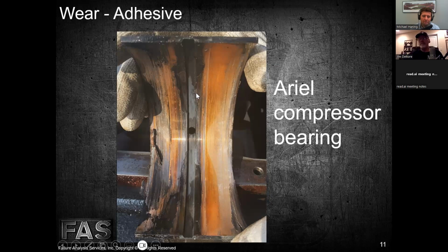We see all sorts of different issues related to crankshaft surface finish, clearance issues, alignment issues, soft foot issues that are causing alignment issues or potential deflection of the frame or case or of the engine block in an engine that tend to reduce clearances and apply load unevenly across a bearing, or just the fact that we don't have lubricant present or the lubricant has been contaminated.